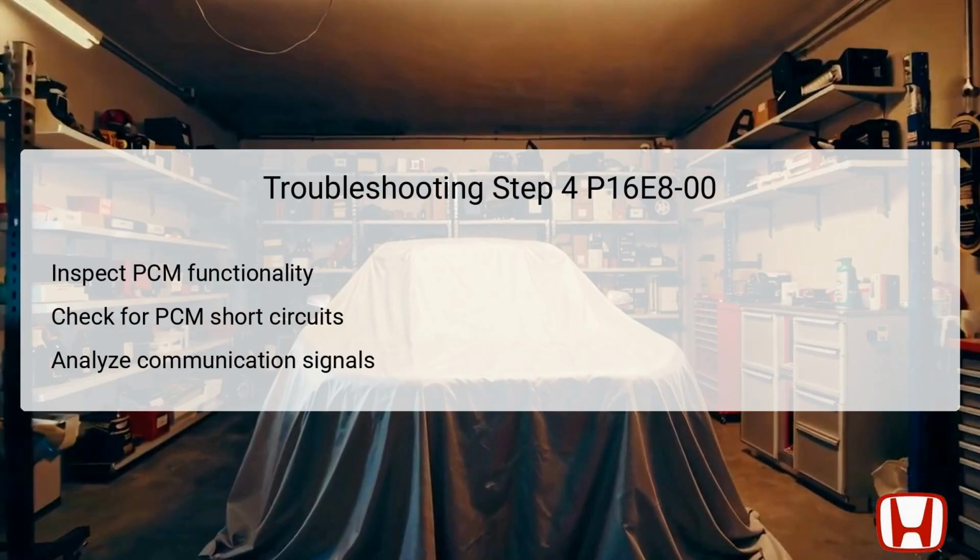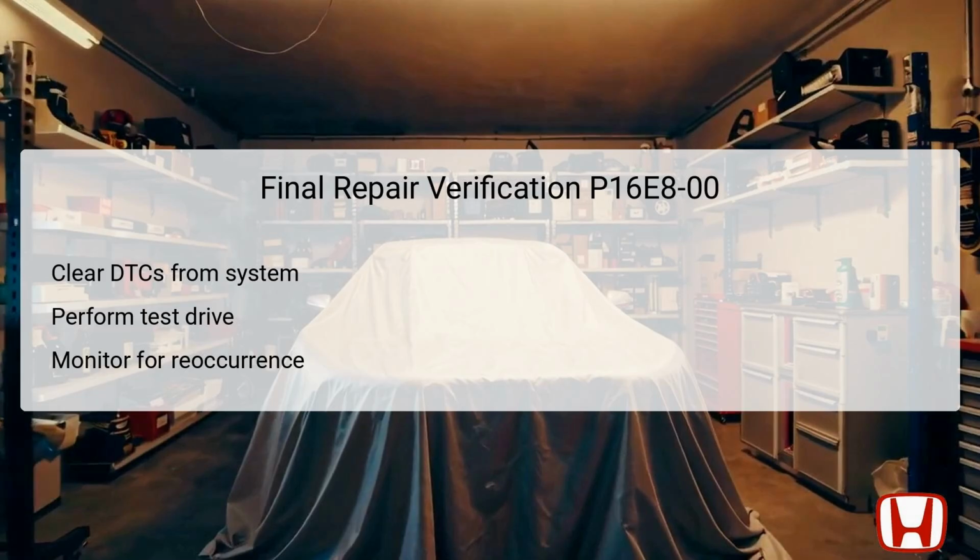If the PCM exhibits abnormal behaviors, such as failing to interpret signals, it may be the primary reason for the DTC. This comprehensive investigation ensures that all angles have been covered before proceeding to component replacement or reprogramming of the PCM. Final repair verification is crucial to ensure that the DTC P16E8-00 has been fully resolved.